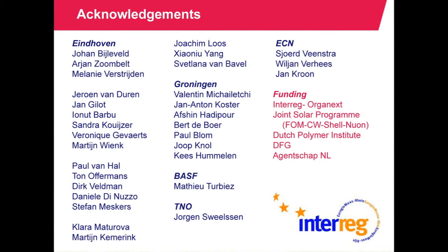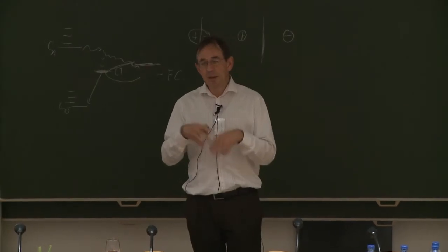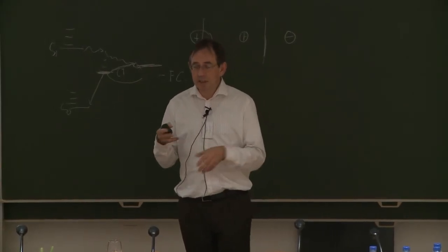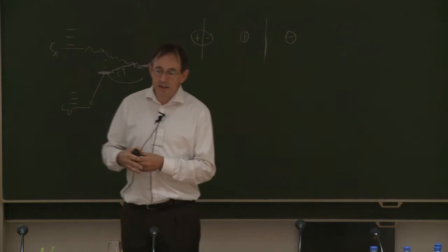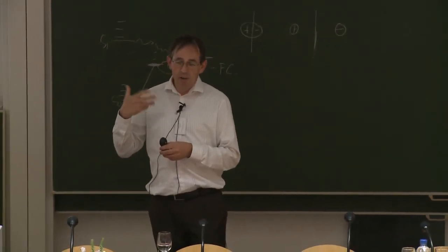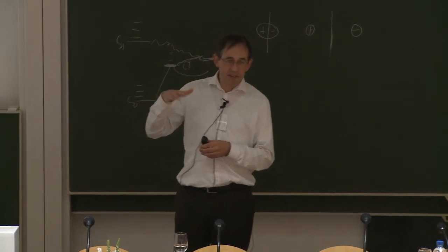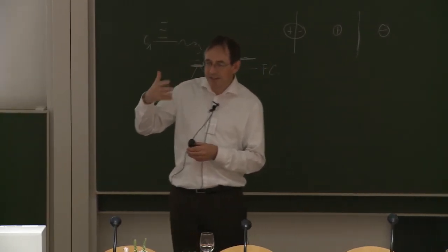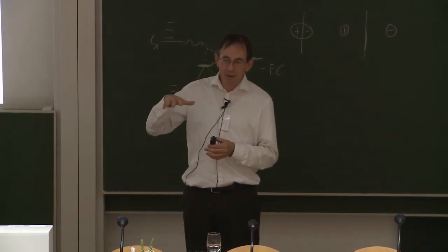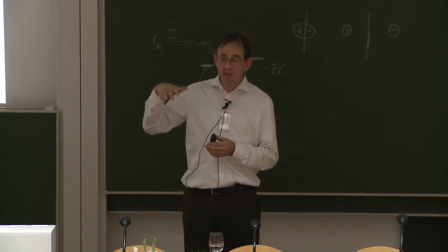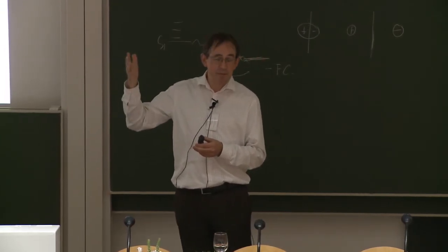So if we come back to materials that give us 6, 7, 8%, and we would have one wide bandgap and one small bandgap, then we would definitely be able to put that into a tandem that gives you an improved efficiency. If you are realistic, and the maximum of a single junction cell would be 12%, and we would have 2 of them, then we could raise the efficiency of a tandem cell maybe to 15% or something.